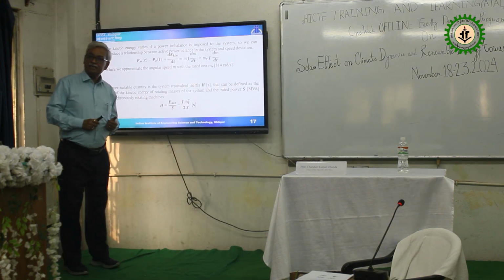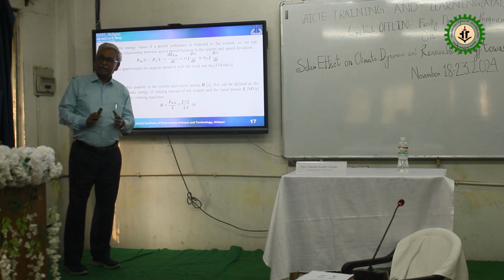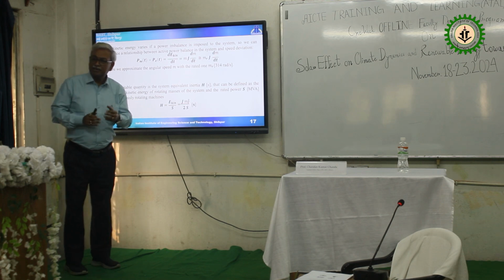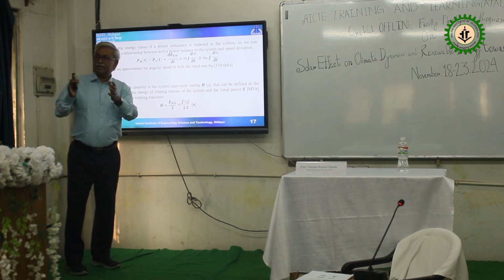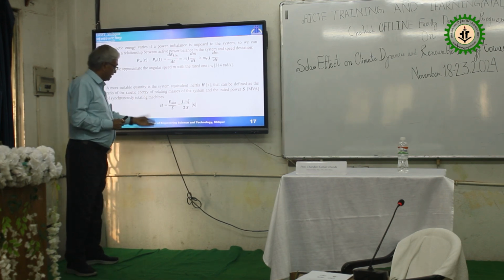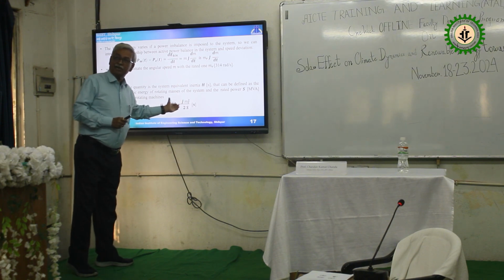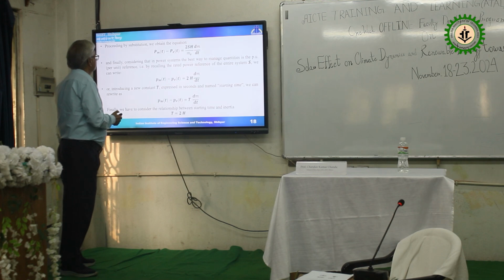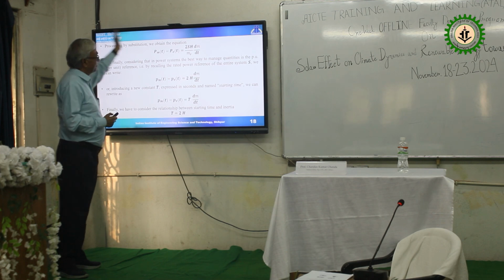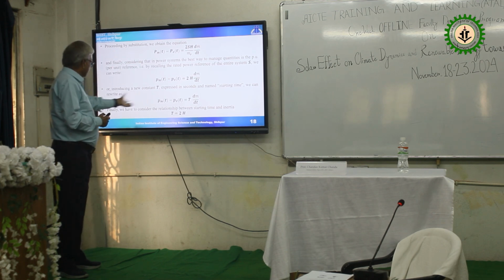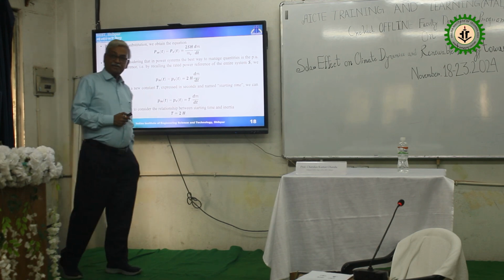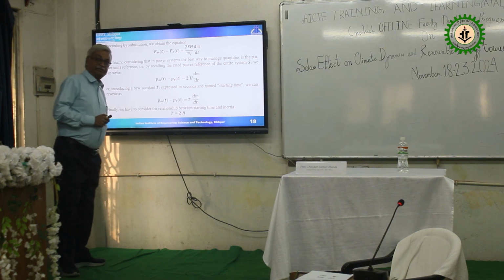So H is basically the inertia constant we define, and we assume that throughout the day or throughout the system, whatever may be the load, whatever the speed of the turbine, H will remain constant. There is a little assumption here, but for simplicity's sake we can define H this way. And you know the unit of H is seconds. With these mathematical substitutions of the H value in the original equation, we finally get a relation. This T, the torque I have defined, is nothing but 2 times H.